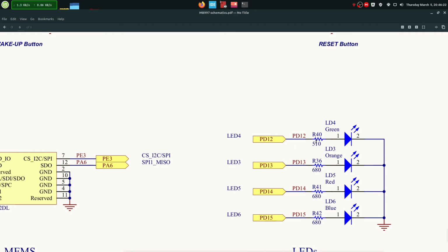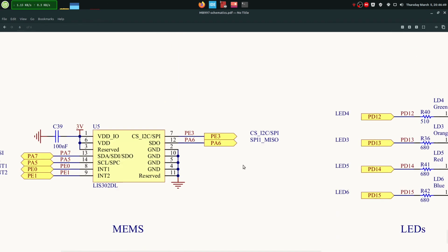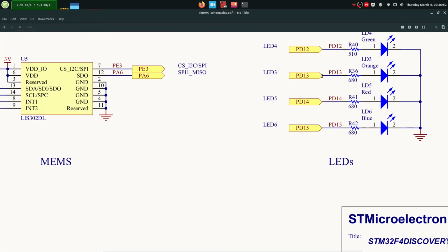So usually we would see these resistors for trivial things. That's why there's this resistor over here. It's 330 ohms, and if it's used as an input, no current's gonna flow through anyway, so this is like a short circuit basically, so it's not very usable. Why would you put it there? This is simply so that if something happens, this pin is protected by at least 330 ohms.